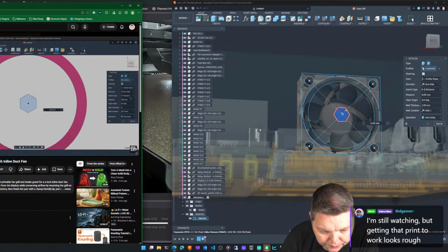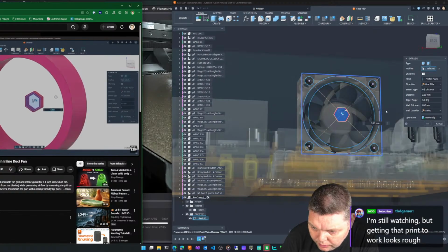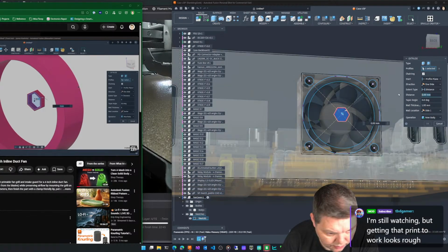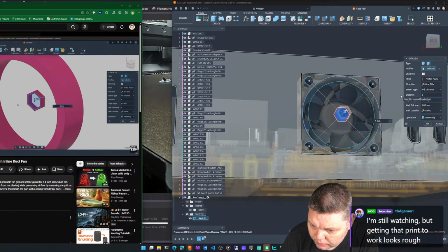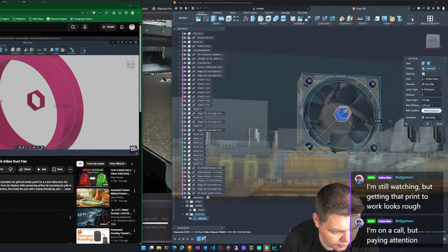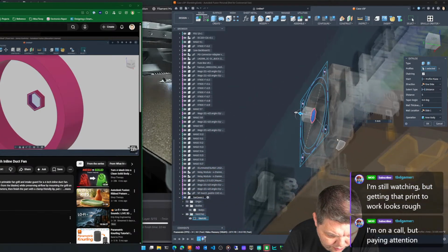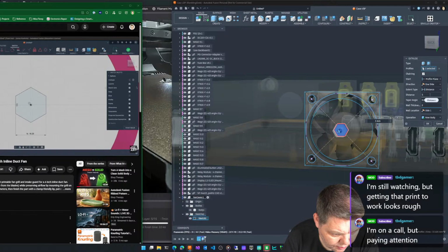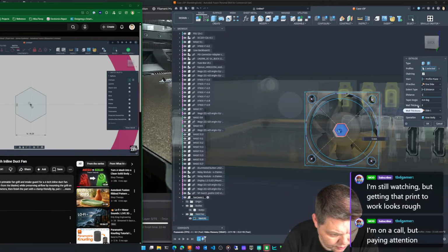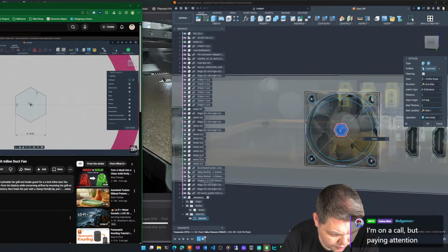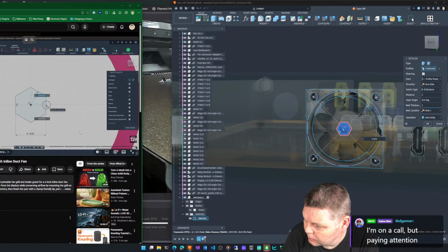2, and the distance will be 5. We now have an extrusion, and it matches that original 5mm extrusion in that direction. We'll press OK. We want to pattern this, but we don't have any axes that would pattern this well. So in that original sketch, if I edit it, I can press L for the line tool. We'll draw some construction lines. I'll draw from the center here to the midpoint, then from the center here to the midpoint.